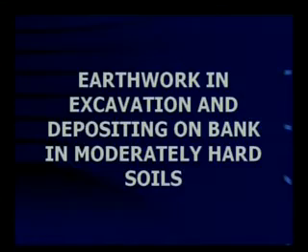Yes, where do we have to excavate? The first thing would be under the head walls. You need to excavate under the head walls. The next excavation would be required under the pipe. Before you fix the pipe in position, you have to lay a thick layer of granular material so that the pipe is in position. Where else do you need an excavation? You need to excavate under the apron on the upstream side and the downstream side. Is that okay? Now we'll move on to the next slide.